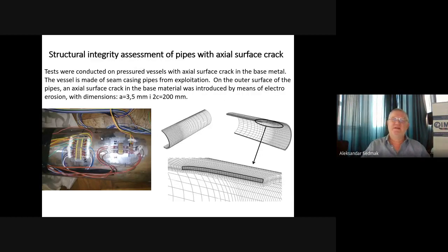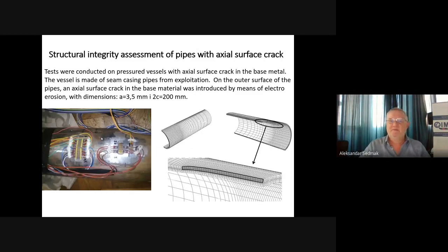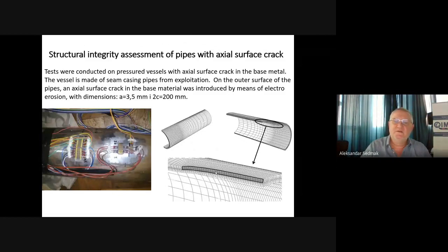And there was extensive research about this, another doctoral thesis. We have measured J integral by measuring strains. It is so-called direct measurement of J integral. And also we made a numerical study, three-dimensional finite element method, including XFEM later on to calculate fatigue crack growth.